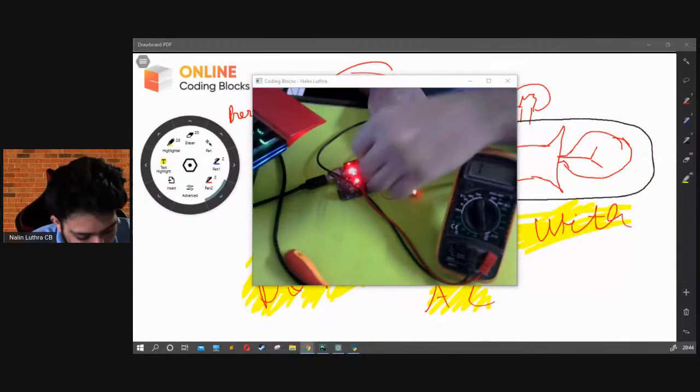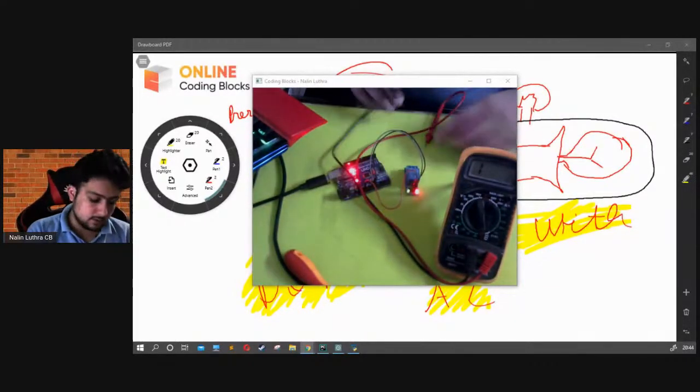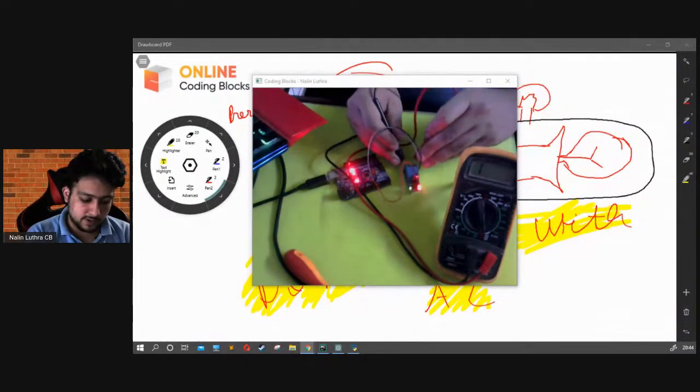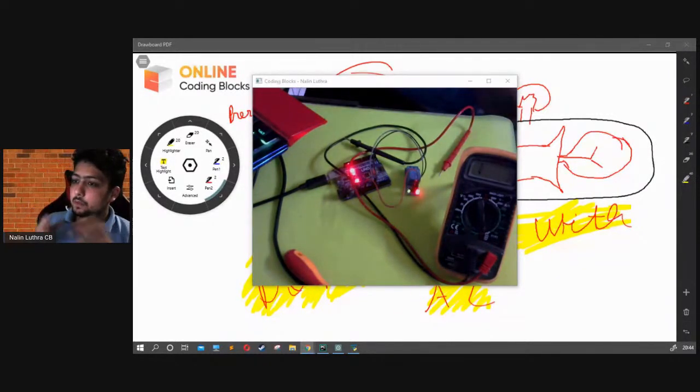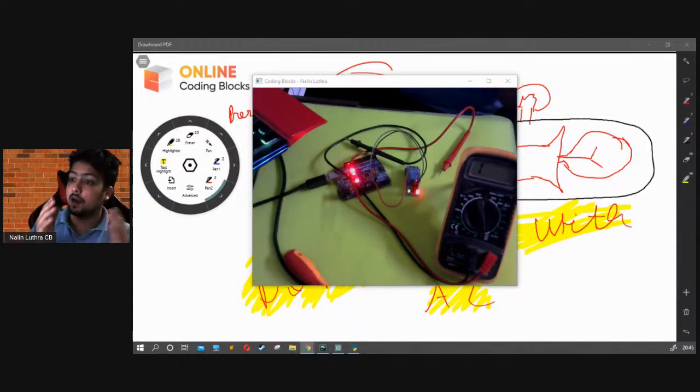So when I connect it with this one, let's connect this one. Now when the green light switched on, I get a connection from here. I don't get it from here or here, I get it from here. As you can see, we get a connection depending upon what we are doing. When we give ground, the connection switches. When we don't give ground, the connection switches back. And that's the idea behind the relay.